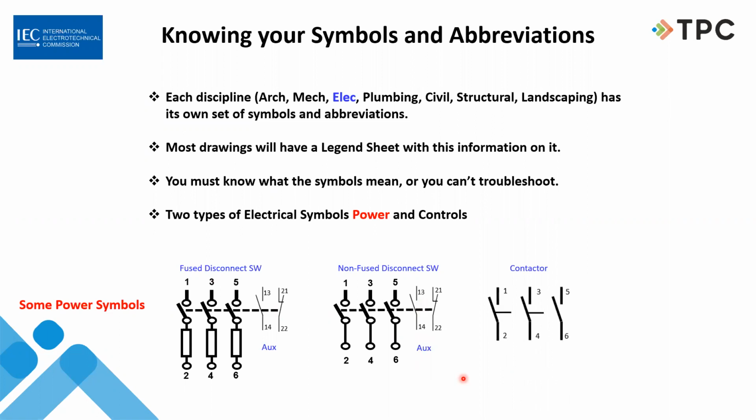This is just a contactor, okay? So a lot of you might have lighting contactors in a building. So this is a symbol for it. And again, our 135, 246, same thing. And just remember that this particular one is just a symbol. In a print, you'll probably get ratings and things, but not just on this symbol.